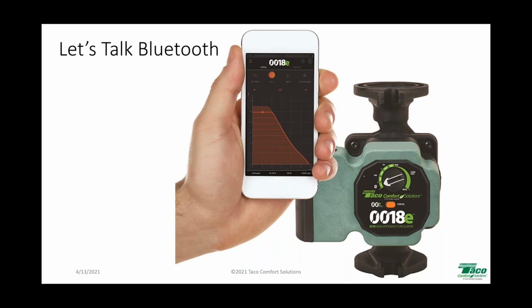You have multiple operating modes. You have proportional pressure, you have constant pressure, and you have an infinitely variable fixed speed setting if you're using it as a zone pump. So you have different ways to program it without the app. But if you put it into Bluetooth mode and connect it to your phone or an iPad or any kind of device, Android or iOS, you open up a whole new world of possibilities. So without the app, you have two constant pressure settings, right here, you see them.